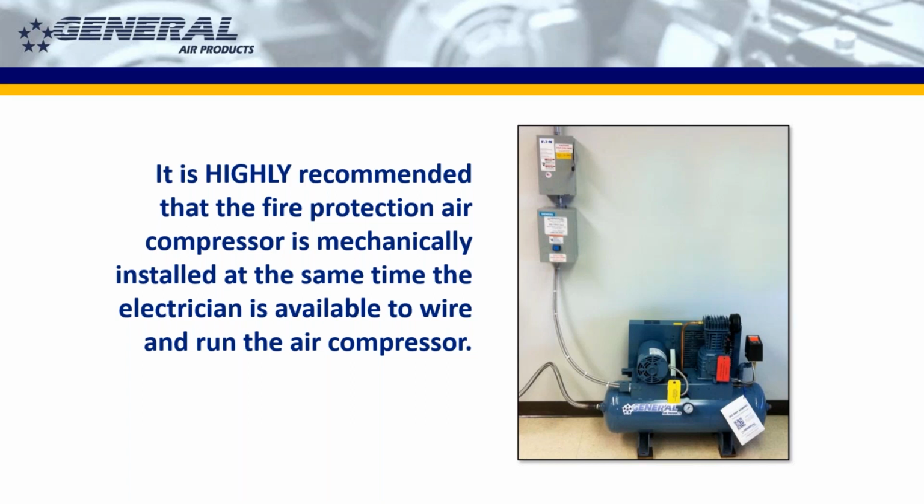I know that this is somewhat impractical on some job sites, but if you can arrange this, it is worth the while to do so, because I would say our number one overall reason for return is wiring issues. The number one return in and of itself is probably people not putting oil into the pump at the right time. But if I were to collect all of the oil versus electrical problems overall, people miswiring it, things like that are going to be the number one thing that we get phone calls and returns about.